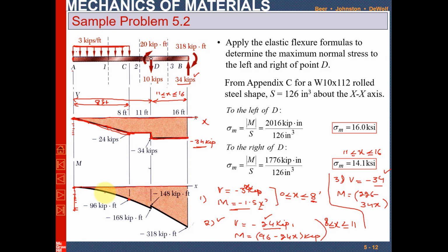So how will you join them? You will see that this shear force is a linear equation, so definitely the bending moment will be a curve, or it will be parabolic. But here it is drawn like this one. Why is it not drawn like this? This one is in clockwise direction and this one is in counterclockwise direction. So I will explain this.